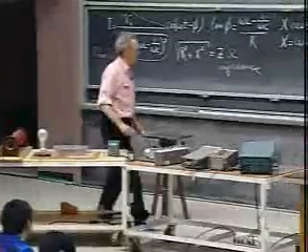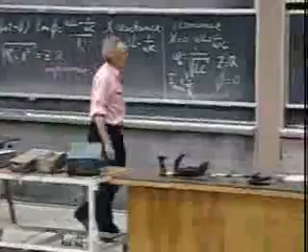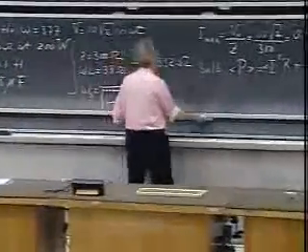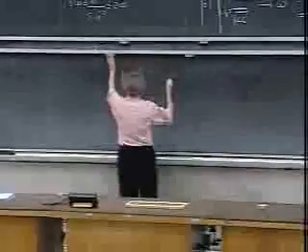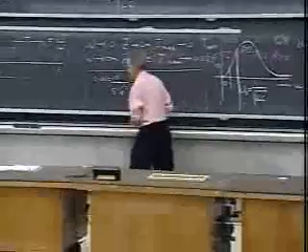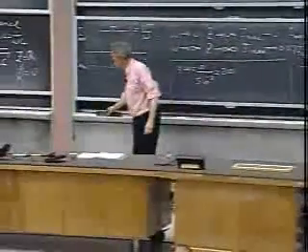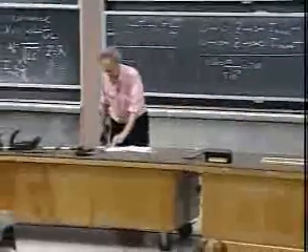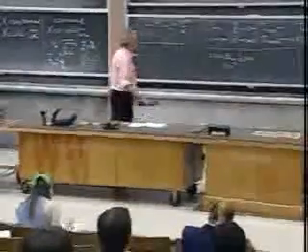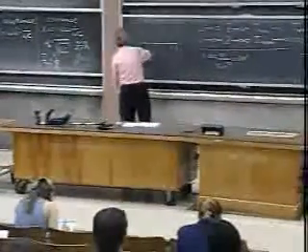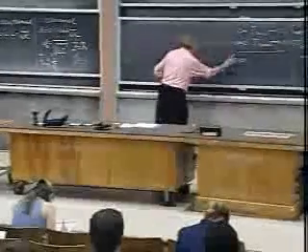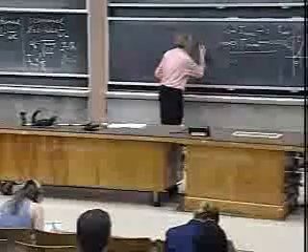Great. So now comes the question, what could we do to get the system back on resonance? Well, we know that our driving frequency is 377 radians per second. And so what we could do, we could change the C in the circuit, or we could change L in the circuit.